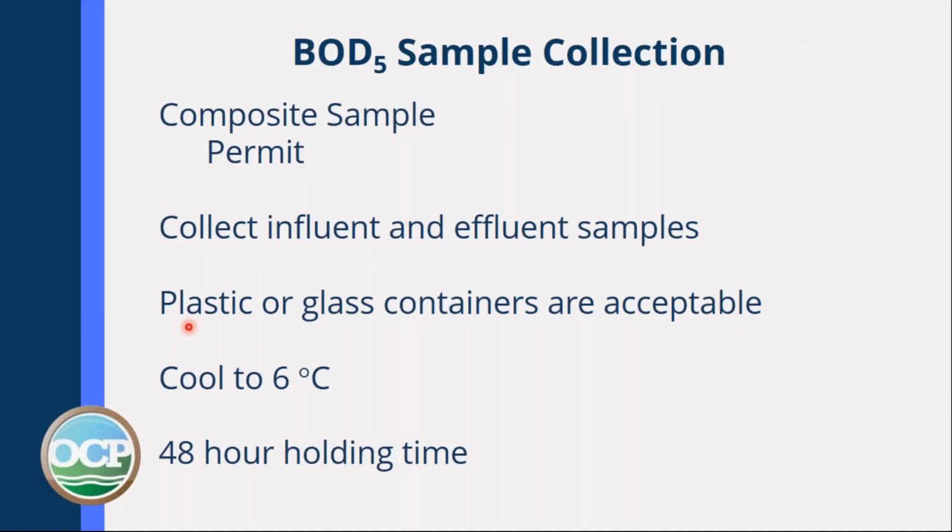So the sample collection for BOD, like TSS, is a composite sample. Again, you're going to collect the water coming in and the water as it's being discharged. Plastic or glass are acceptable. Again, you're going to cool to 6 degrees centigrade, but the holding time is only 48 hours or 2 days. But once you've sampled these, you're probably going to test it quicker than that.